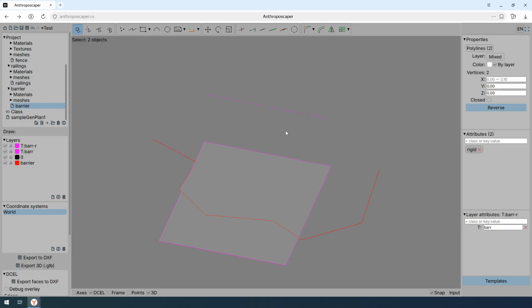And here it's worth clarifying the difference, because rigid can be placed in two spots. Rigid on the axis makes each copy of the template rigid as a whole. The copies don't deform, hold a fixed length, and don't bend along the line. And rigid on a single mesh can bend along the path, but tries to hold its shape and doesn't skew.